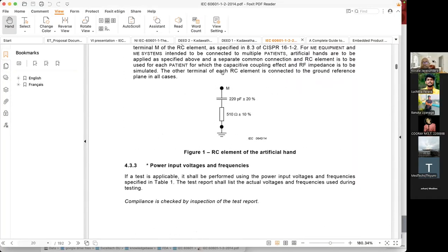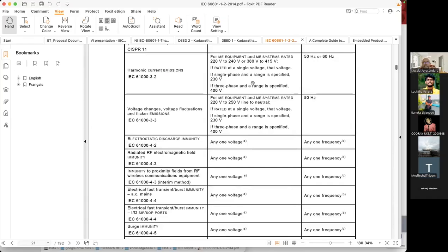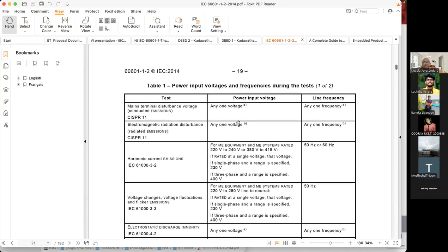So when you are testing for human hand, this is for electrostatic discharge testing. This is for artificial hand. When you touch the device, it should not electrocute you. And if your hand is charged to 20,000 volts, which happens in other countries, not in Sri Lanka, in low humidity countries, it should not discharge to the device and burn the device. For that, the testing should be done with exactly this amount of apparatus. And you have to adhere to this table.